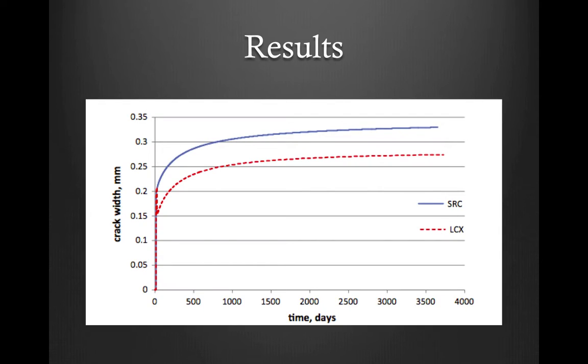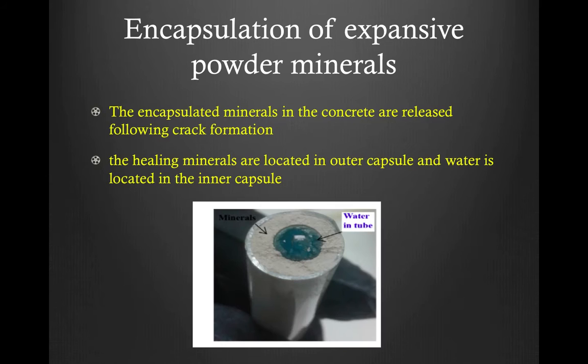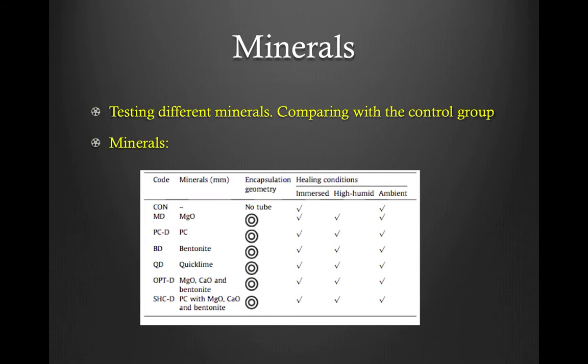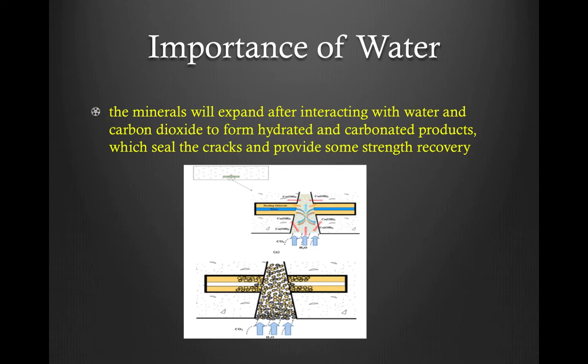Another method called encapsulation of expansive powder minerals. Encapsulated minerals in the concrete are released following crack formation. They will rupture and release expansive powder minerals. Here is a table that displays different testing minerals for the same method. Importance of water in this testing.